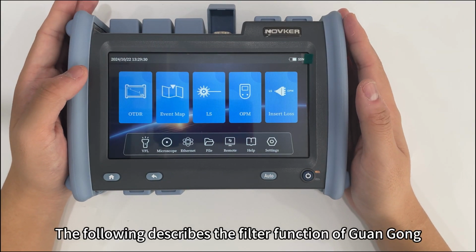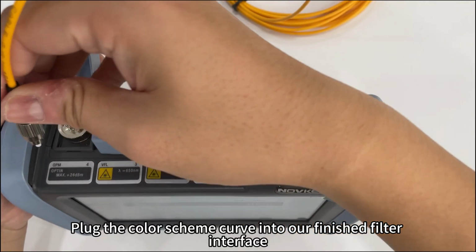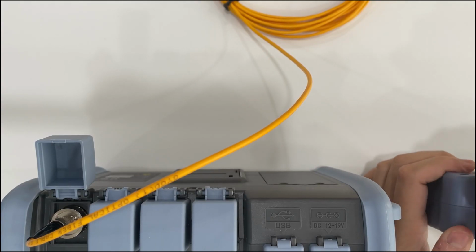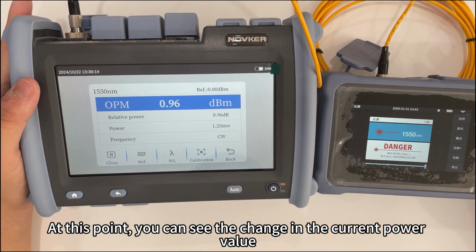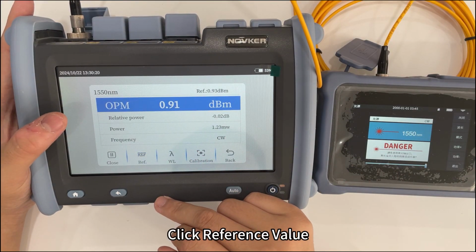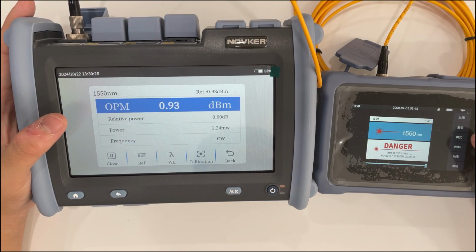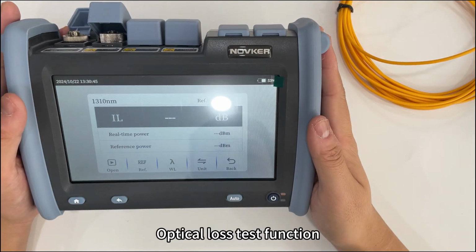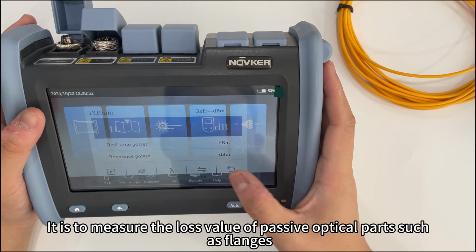The following describes the optical filter function. Click on the optical filter. Plug the fiber into our optical filter interface. Find our light source. Switch to the corresponding wavelength, then 50. At this point, you can see the change in the current power value. Click reference value. The current power value can be set as the reference value. Click to switch the wavelengths. The wavelength can be replaced. Optical loss test function. It is to measure the loss value at passive optical parts such as flanges.